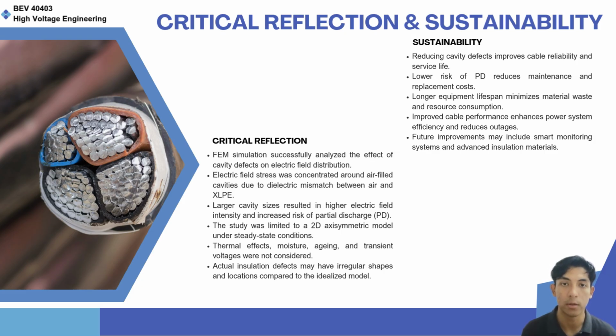Alright, now I'm going to present the critical reflection and sustainability part. We start with critical reflection. So FEM simulation successfully analyzed the effect of cavity defects on electric field distribution. Electric field stress was concentrated around air-filled cavities due to the dielectric mismatch between air and XLPE. Larger cavity size results in a higher electric field intensity and increased risk of partial discharge.